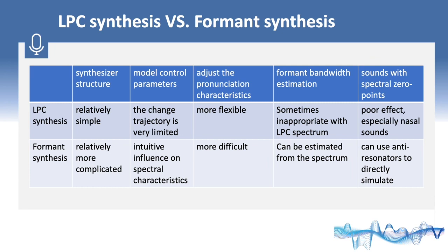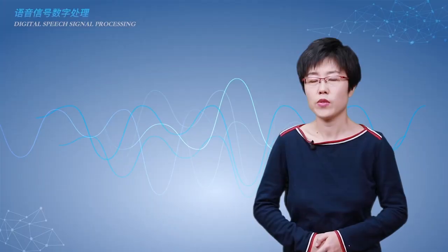Fifth, the all-pole model of standard LPC has a poor effect on sounds with zero-point spectrum characteristics, especially nasal sounds. The formant synthesis method can use anti-resonators to directly simulate the most important spectral zeros in nasal sounds, improving the synthesized sound quality.